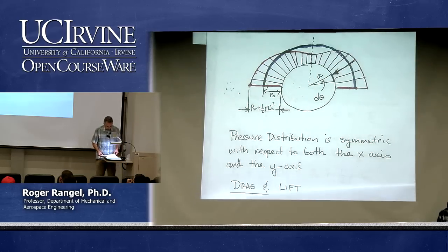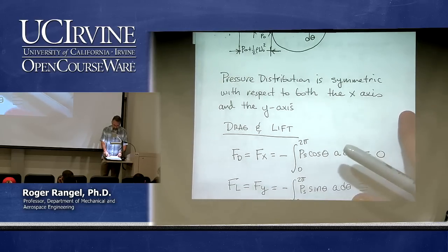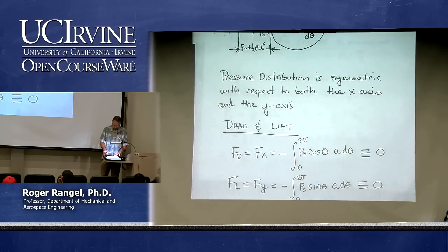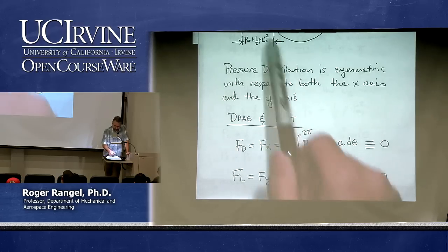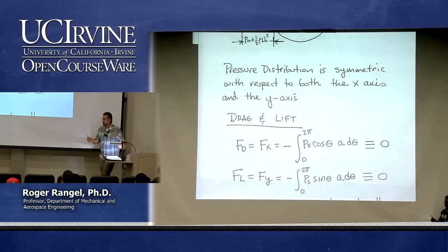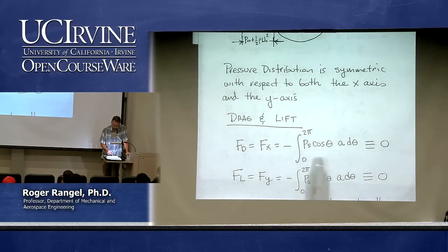And I can show that if I actually go through the rather tedious process of finding those forces, the F sub x and the F sub y. What I would have to do is, of course, integrate. I cannot just say pressure times area, because the pressure varies, but I have to integrate the pressure over the area. Okay, I'm just showing you here what the integrals look like if you were to do the integration to find the force.